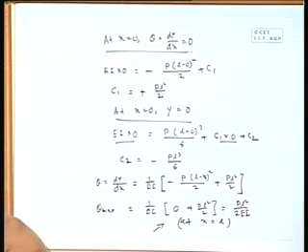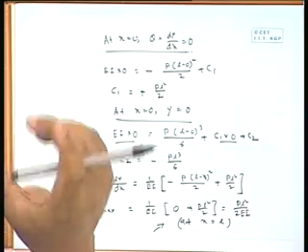Now, this is one quantity, P L square by 2 EI, that is a cantilever subjected to a load at the free end, we are getting the maximum slope there, P L square by 2 EI. This is one of the very important terms. There are some very standard cases. This is one of the standard cases, and the value is one of the standard quantities. So, if we try to solve a relatively difficult problem, some of the quantities like this P L square by 2 EI will be utilized later on.